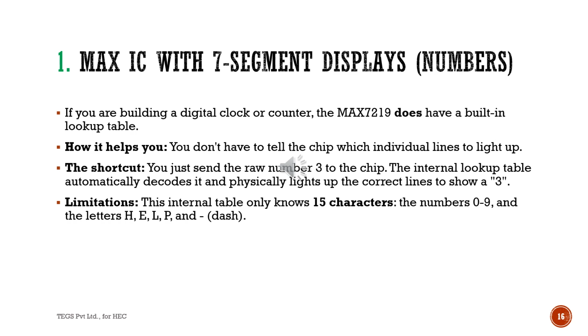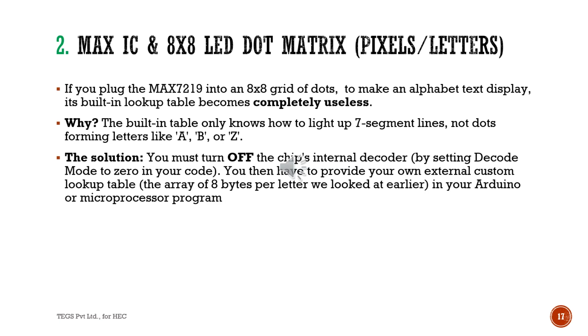Limitations. This internal table only knows 15 characters: the numbers from 0 to 9 and the letters H, E, L, P and dash. If you plug a MAX7219 into an 8x8 grid of dots to make an alphabet text display, its built-in lookup table becomes completely useless.